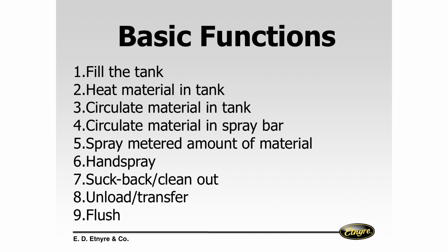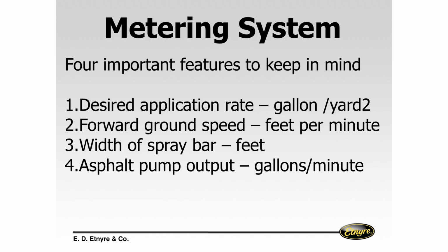So every distributor on the market has the same basic functions. You're going to fill the tank, you're going to heat it, you're going to circulate it, you're going to spray it in a metered application, and that's what we're after, our metered application. You're going to suck it back, you're going to clean it out, and you're going to go home. Every distributor on the market has the same basic functions. But it's the metering system that we really want to pay attention to.